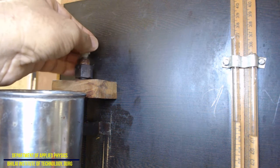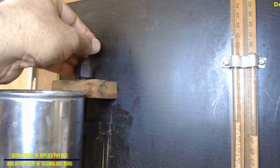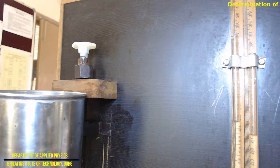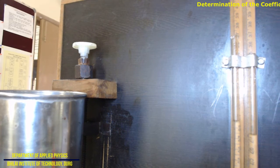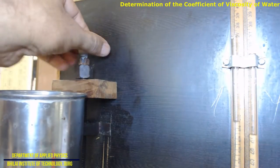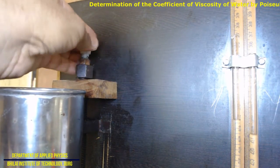Now the lower meniscus is at 28 centimeter, and the right side meniscus is still at 27. We have to keep it 27. So in this way we have to create a difference of say 1 centimeter. What I see, the left level has also increased, so we are going to increase continuously the left level, so that the difference of 1 centimeter is created.